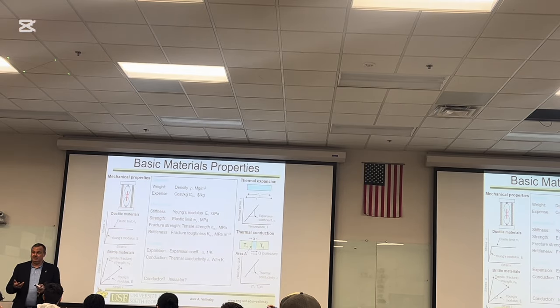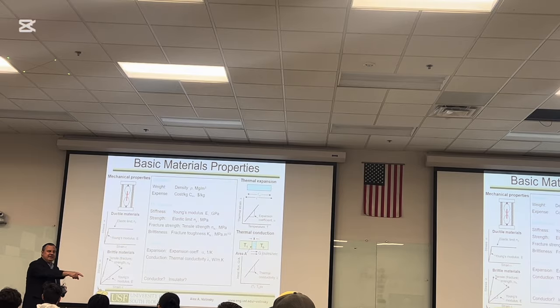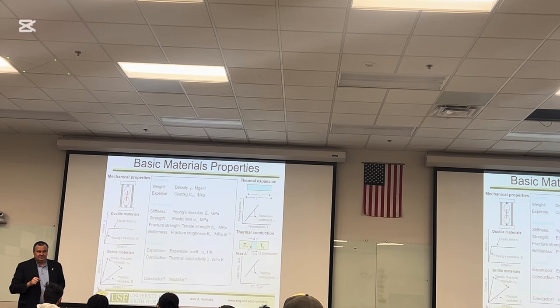Does anybody know? Small, which is achieved how? The lever, that's good, and besides the lever, what else is there? It's already weakened. How is it weakened? It's like a little cut. A little cut outline that gives you stress concentration, similar to the perforations on the toilet paper.